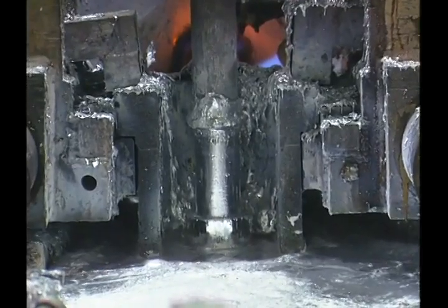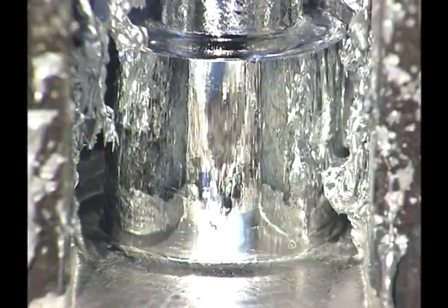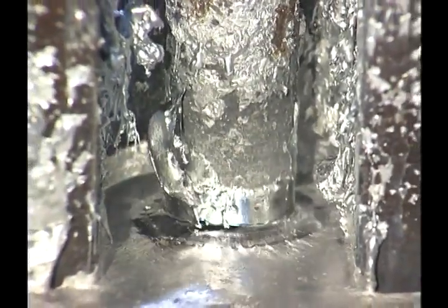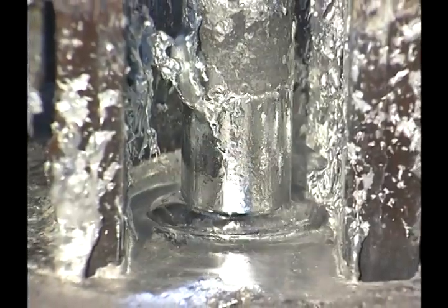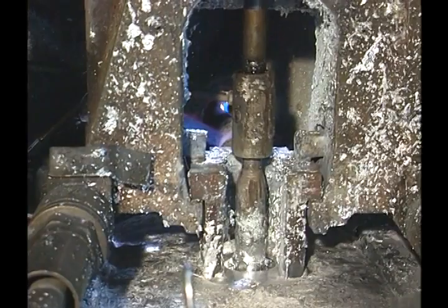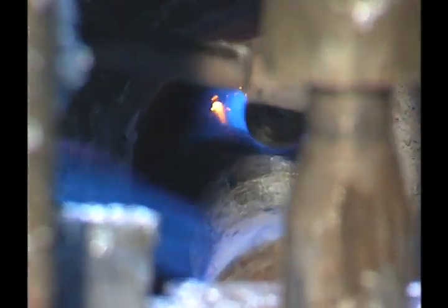The plunger end of the injection system and the lower portion of the transfer pipe are submerged in the molten metal. When the plunger rises, a charge of metal enters the pipe through a submerged port. When the plunger descends, it closes the port and drives the charge into the die, forming the part.